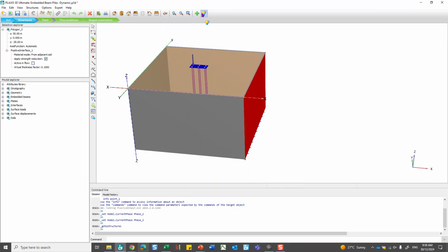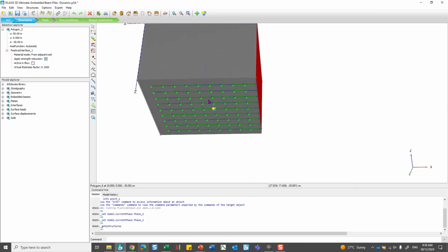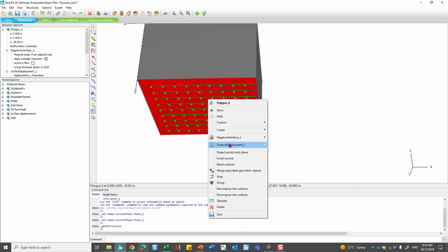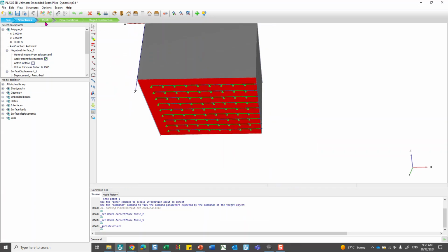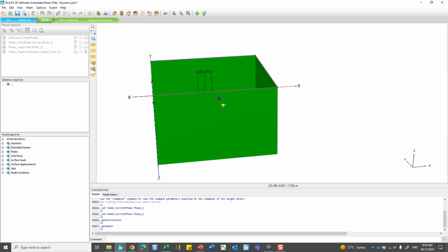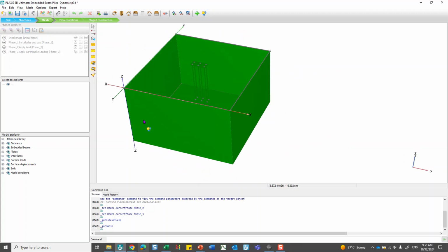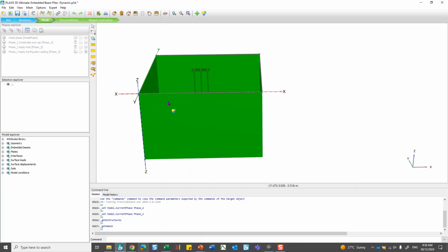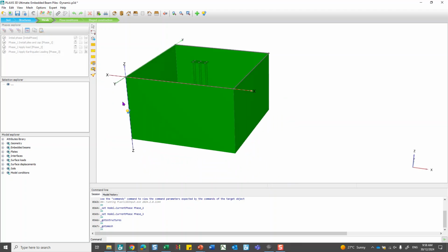And at the base of the model, I have applied a load here in the form of, if you see, surface displacement. So I have this done already, and then I generated the mesh here. As you can see, I did not select any points for curves or anything, because here all I'm interested in is these piles and the critical combinations.